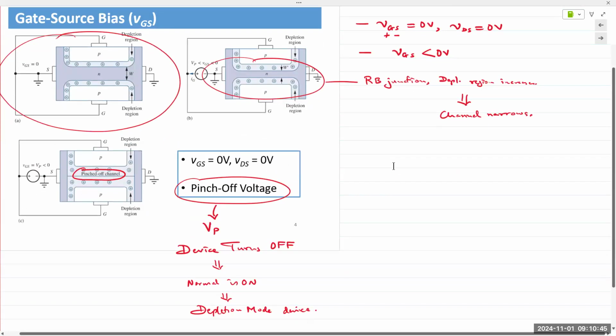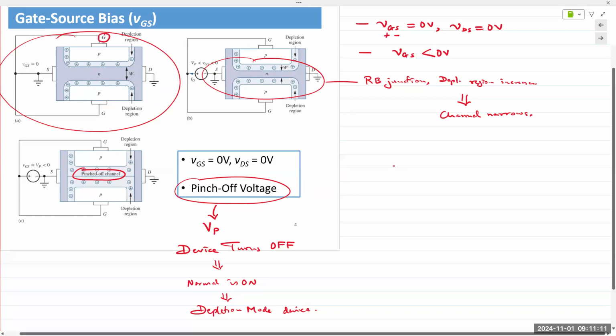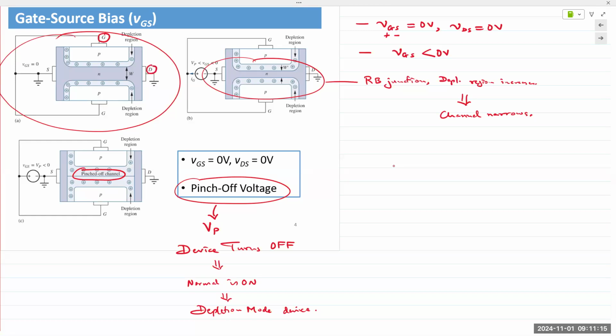So, brief recap. JFET is an N-channel device. You have a semiconductor of N-type material, and we implant P-type material in there. That creates a gap between the two P-type materials, meaning there's a channel between the two P-type materials. The two P-type materials are connected together, and we form a terminal we term as the gate. The two ends of the channel are labeled as drain and source.